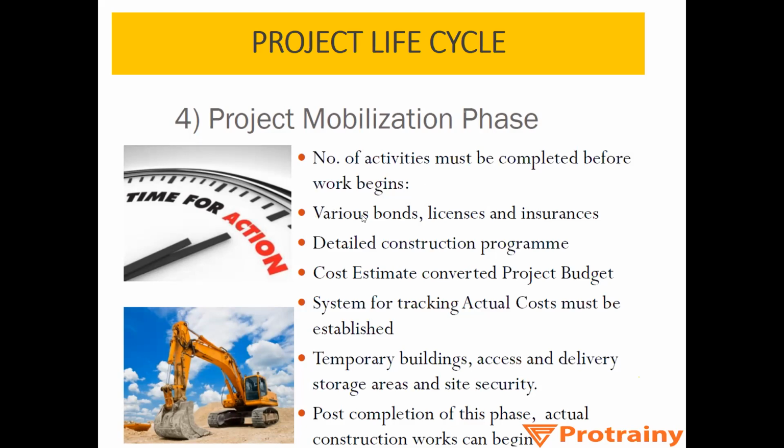That is, various bonds, licenses and insurance you need to take, a detailed construction program you need to prepare, the cost estimate converted into a project budget, and a system for tracking actual cost must be established, how you are going to track the actual cost of the project. You need to set up temporary buildings, that is site offices and labor hutments, etc. A storage area where you will store cement and other construction related material. Then post completion of this phase, actual construction work starts. So this was the fourth phase, which is the project mobilization phase.